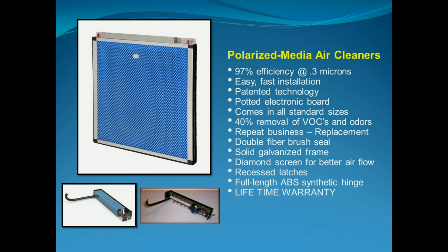The power head itself is a potted electronic board. You can see it on the graphic screen here. We use potted electronics, meaning that an open electronic board, if you put it in ductwork, is going to have moisture, mold, mildew, dust, dirt, and debris landing on it. It's going to be susceptible to all the different nasty components that land on it. Unless you're cleaning it off every 30 days, it's eventually going to heat up and burn out.